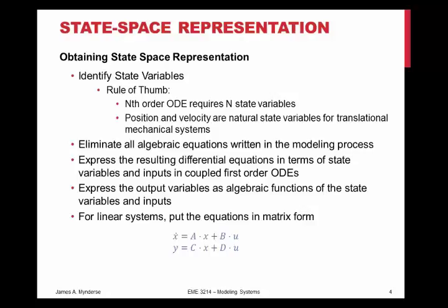Once you've got your state variables, you need to eliminate your algebraic equations, and you need to convert your differential equations into differential equations in terms of the states. When you do that, you should end up with relatively simple equations that you can split into first-order ODEs, and you'll see that in the examples. Once you've got your first-order ODEs for your state equations, you write your output equations in the same sort of way. You're going to put them in terms of the state variables and the inputs.